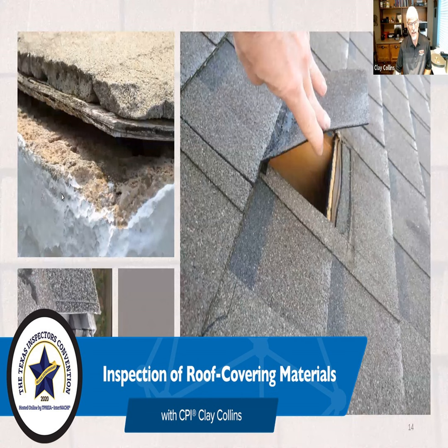And then down here, the purpose of this slide or photo is to show you how much granule accumulation there is here. Those roofs are just almost bare of the granules, and here are close-ups over to the side. You can see how full that is. That's a worn out roof. What about blistering?